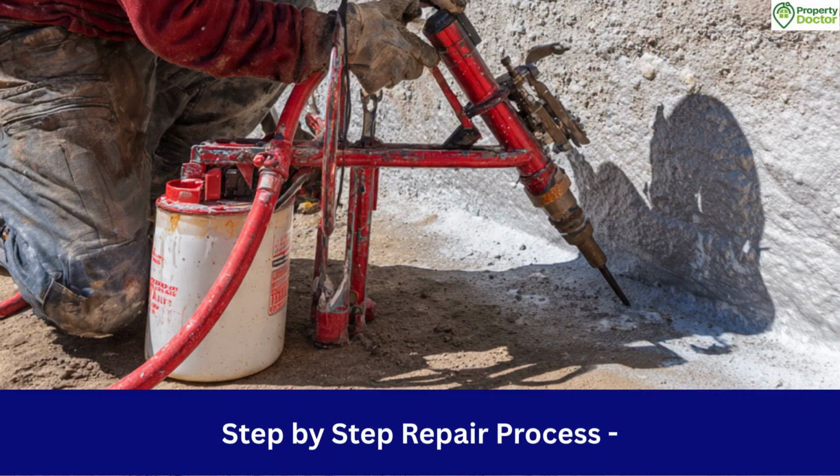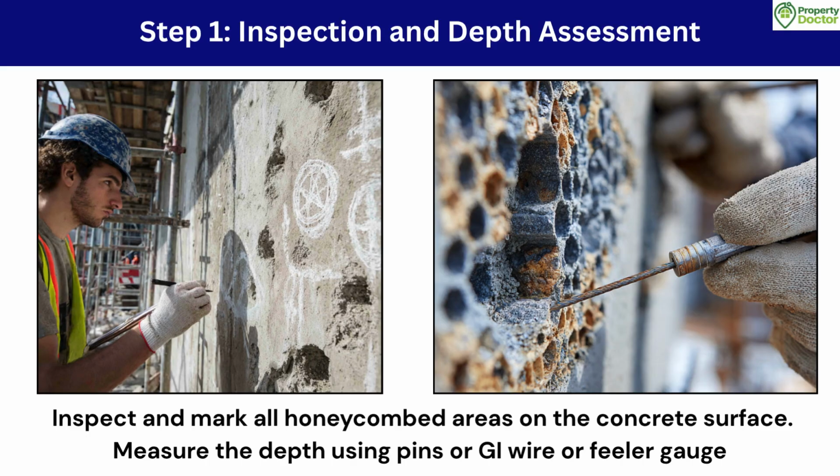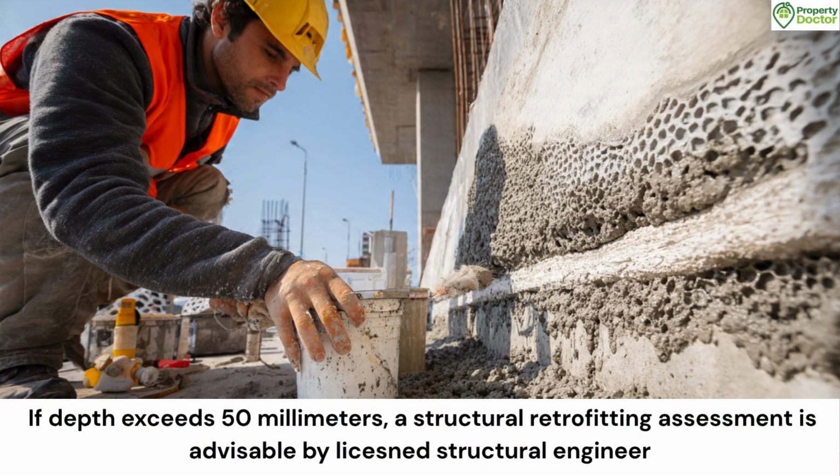Step-by-step repair process. Step 1. Inspection and depth assessment. Inspect and mark all honeycombed areas on the concrete surface. Measure the depth using pins or GI wire or feeler gauge. If depth exceeds 50 mm, a structural retrofitting assessment is advisable by a licensed structural engineer.